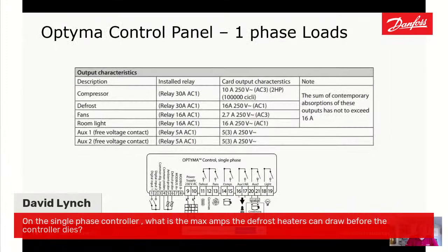Now, David's come in with a question, David Lynch. Hi, David. On the single phase controller, what is the max amps the defrost heaters can draw before the controller dies? That's a good question. Let's just go back a little bit to this one. So this is the one phase controller. Now you can see defrost relay is 16 amps AC1, which is, as we said, resistive.